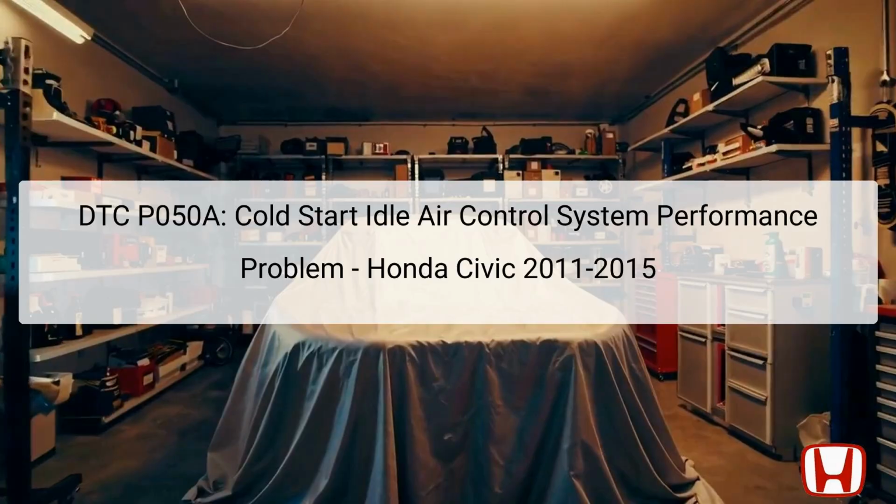The error code P050A signifies a cold start idle air control system performance problem in the Honda Civic models from 2011 to 2015. This code indicates that the vehicle's idle air control (IAC) system is not performing as expected during cold start conditions.